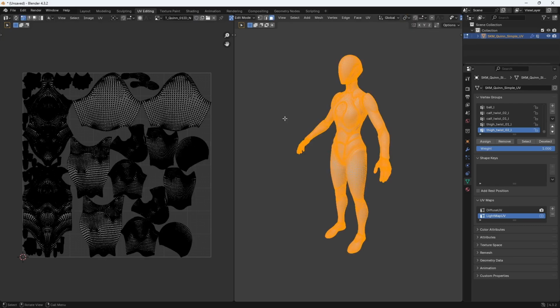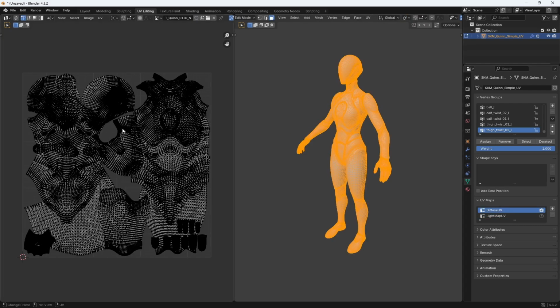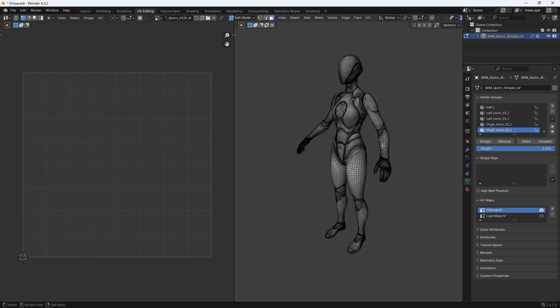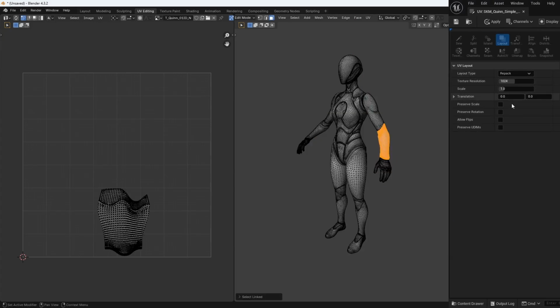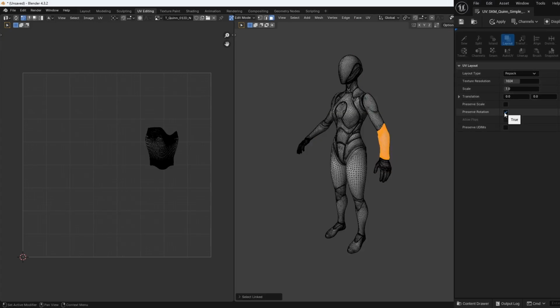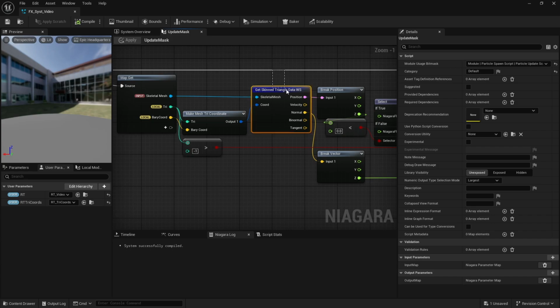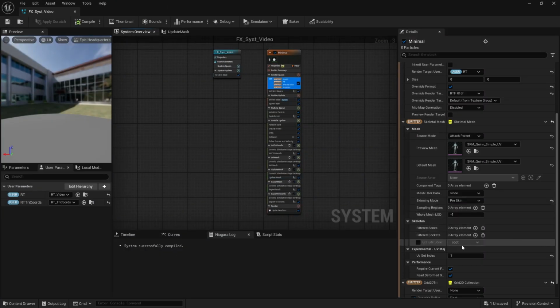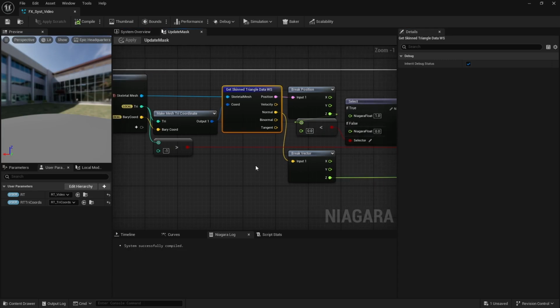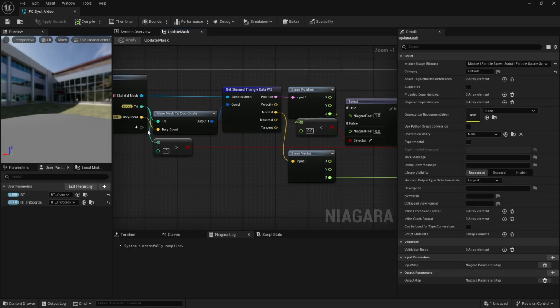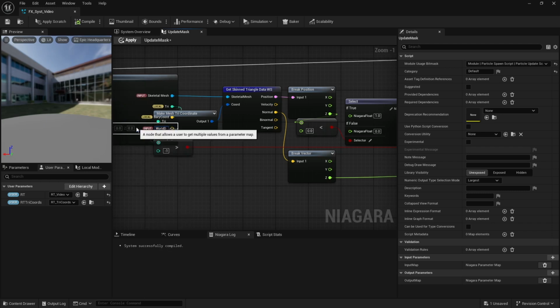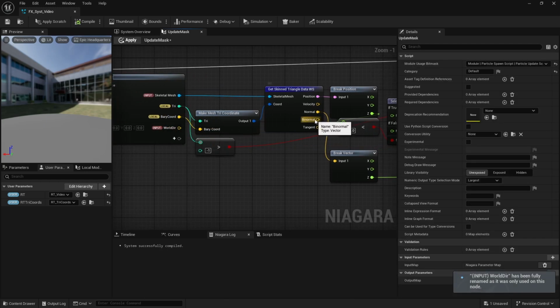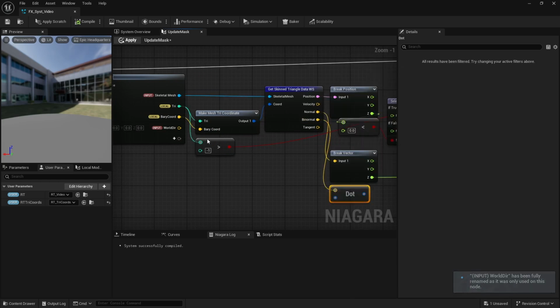And that's nothing too complicated as long as you maintain the same UV orientation in UV1 as in UV0, which I mentioned earlier with the keep rotation option, right? This ensures the normal, binormal and tangent vectors, computed partly based on UV0, despite using the UV map 1, remain coherent even when using UV1. That means we can essentially just get a vector in world space. Then we do a dot product against the binormal to get the U component.